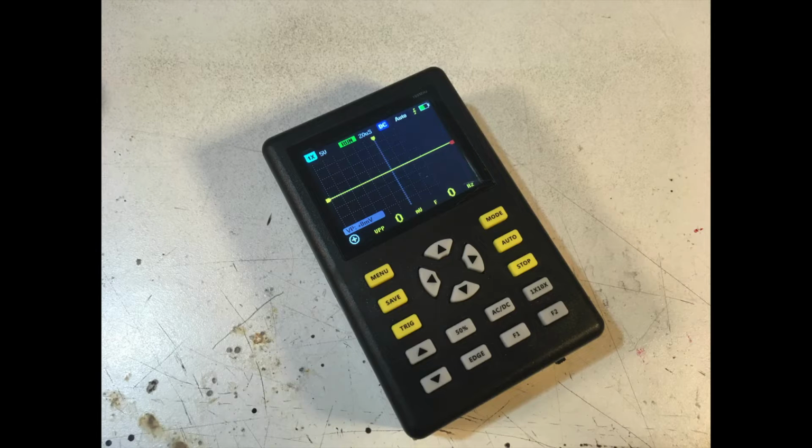It won't consistently measure other things over 100 megahertz. And there's non-linearities in between. Like I said, there's that bizarroness where we had a minus 3 dB point around the low 40s megahertz-ish, and then it started to taper up again, and then got weird at 70 and 80, and then got fine again up around 100 for some signals. So I'm not sure what to call that bandwidth.